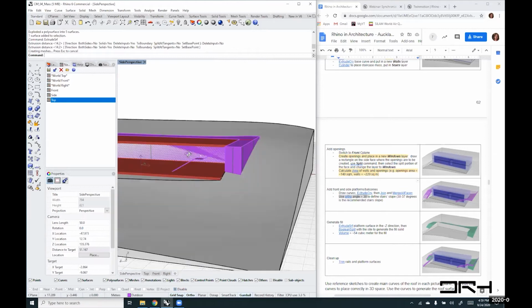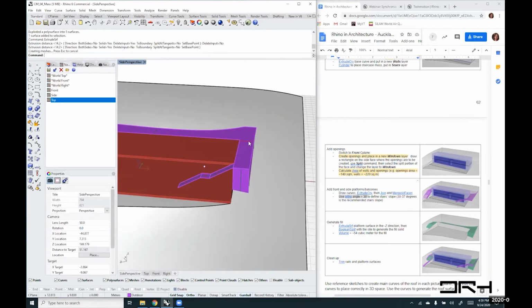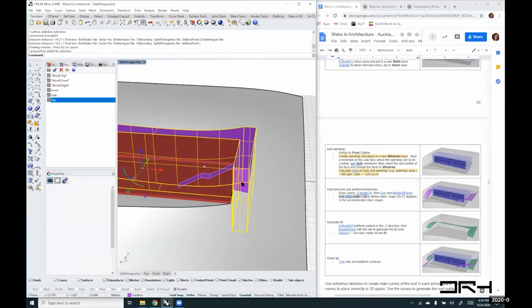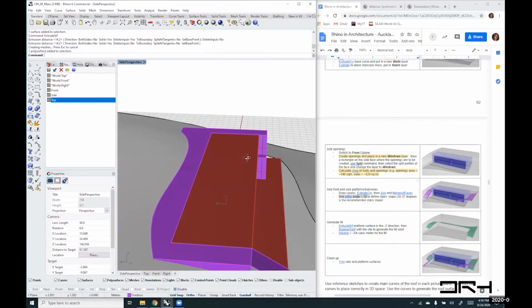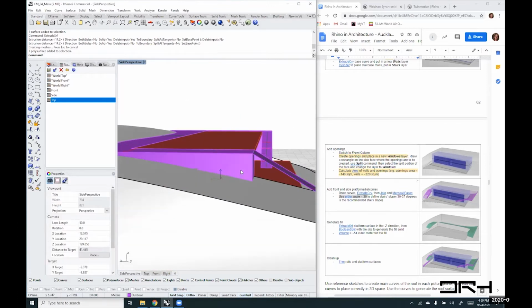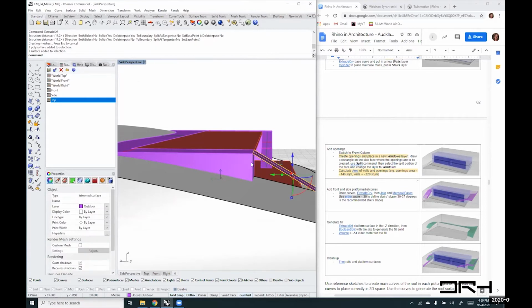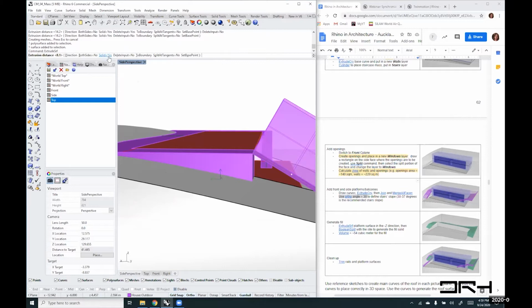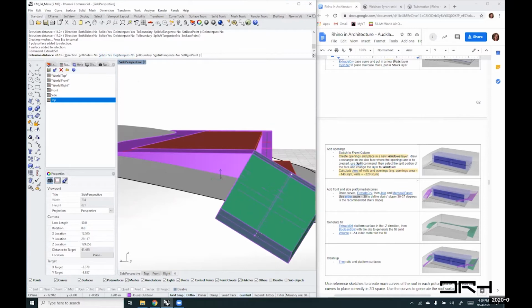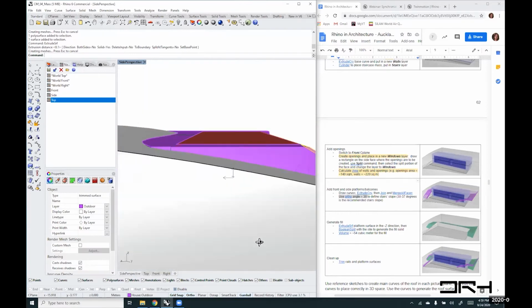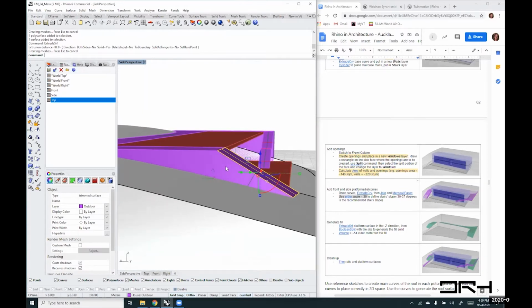So yeah, that's better. Now my platform and the surface are intact, and I created a new geometry down at the bottom to be able to use as a fill. I do the same with this part because it wasn't joined. I'll just extrude down, extrude surface, and make sure it's solid. Do not delete your input, and just extrude it down to generate your surface. You can Boolean union those two.